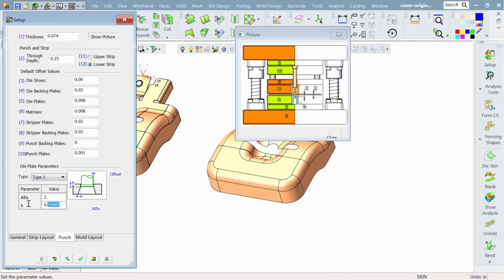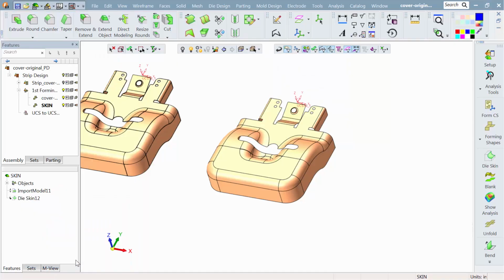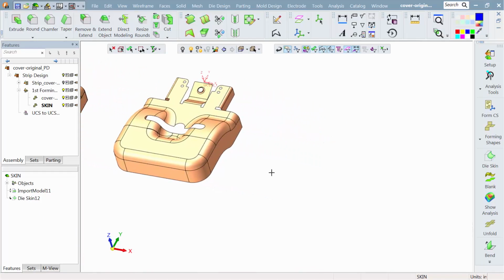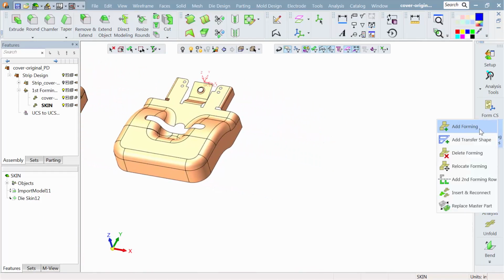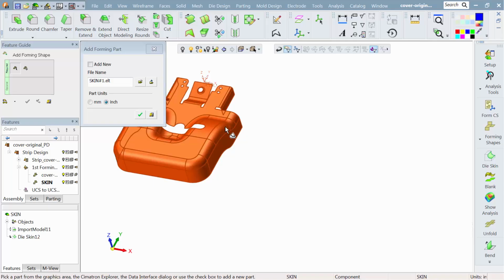condition is. Now we're selecting the type of die steel we want. Typically we see straight land, 1/4 inch with a few degrees of relief. So that's our preference. That's the way we want to design the die. Let's save that in the setup. Now that information is our go-to information throughout this project.